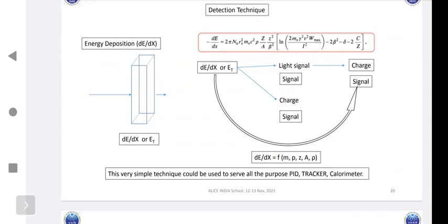Again, you will end up with electrical charge. So ultimately, you will end up with a charge current. Okay. So this current is the signal to you. Some particle passed through a block, lost a very small amount of energy, and this arises as a current pulse, and you are measuring this current pulse.